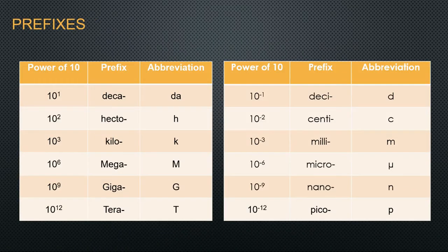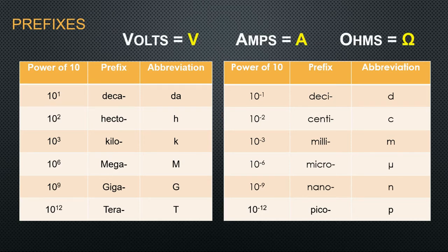Ohm's law works when all of the variables are in whole units: volts for voltage, amps for current, and ohms for resistance. However, these units utilize metric prefixes when they occur in very large or very small amounts. For example, 3.3 kiloohms might be used instead of 3,300 ohms, or 2.5 milliamps might be used instead of 0.0025 amps. When calculations are done using Ohm's law, it's important to convert your values into like units before performing your operation. Dividing volts by milliamps will not equal the correct amount of ohms.